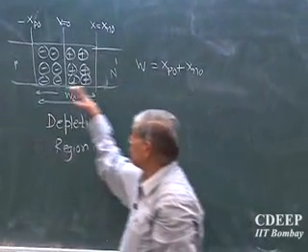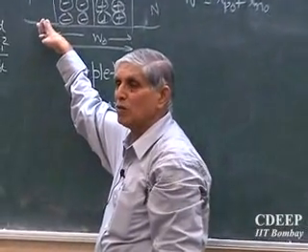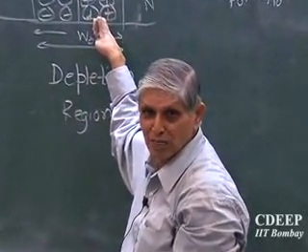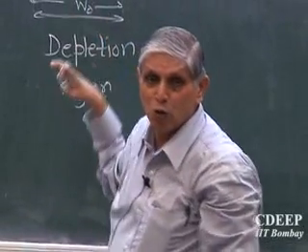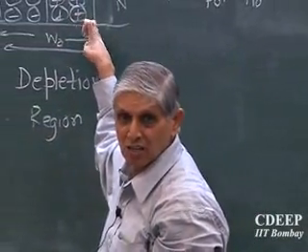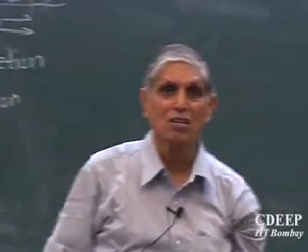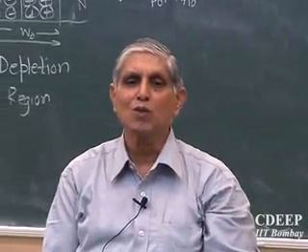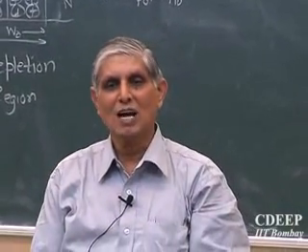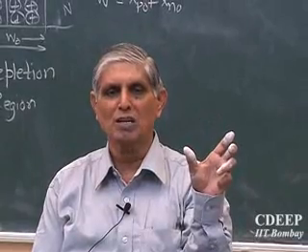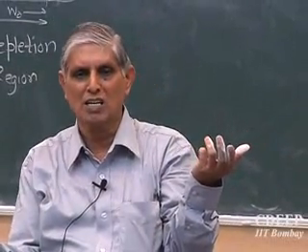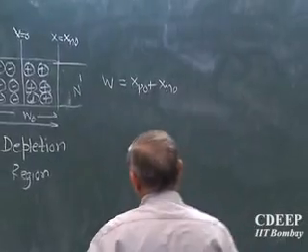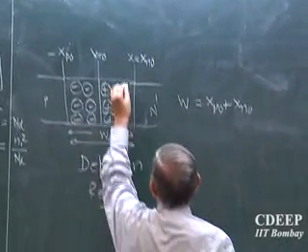On this N and P side, the semiconductor is always satisfying which thing? In the depletion region they are not satisfying. What is not satisfying? Charge neutrality may not be satisfied for holes and electrons but is always satisfied for ions. Outside this, there are electrons and holes on both sides and charge neutrality always holds. Since there is no current flowing because I am not connected anywhere, neutrality says there should not be any voltage drop across the N region and P region, because there are no carriers moving, so IR cannot be created there.